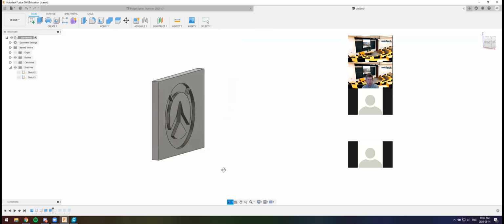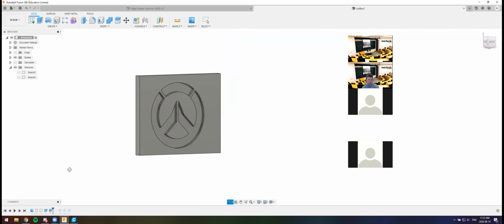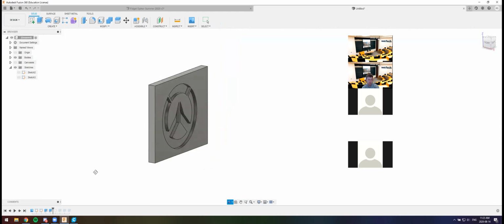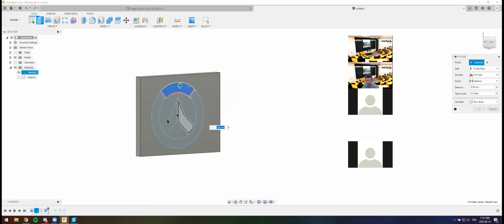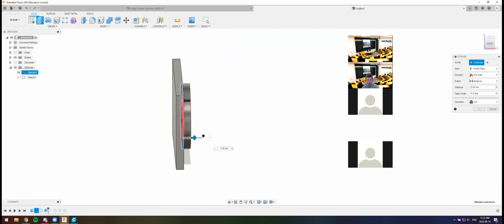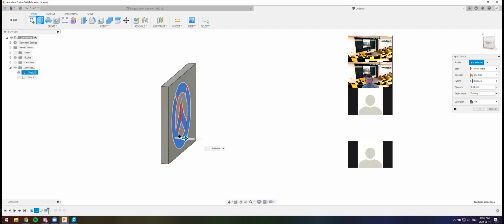There are no restrictions. I understand the part where you have to trace it, but I kind of got lost in the process of engraving it. So engraving, you already know how to do the engraving. It's just an extrude. You click extrude, click on what parts of the sketch you want to extrude, and then you extrude it. Or you can cut it into something.